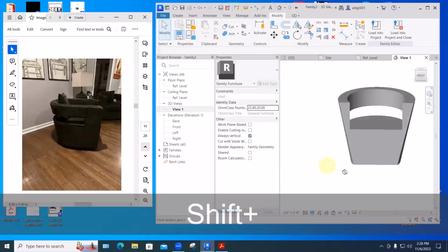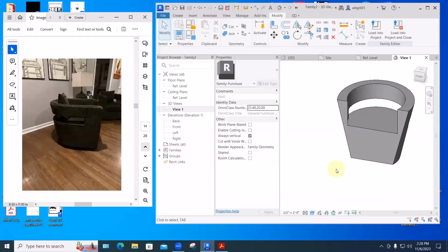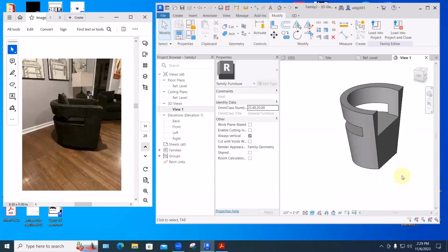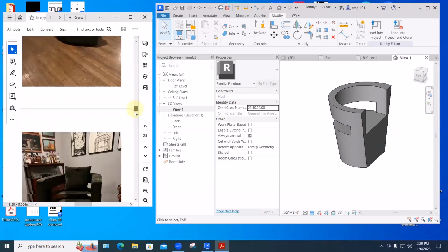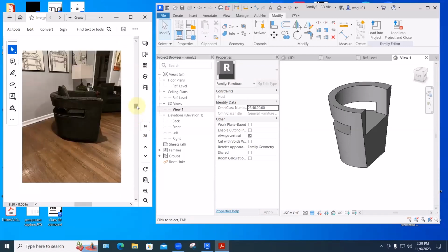Yeah, so to make this as good as possible, this second extrusion would have been tapered as well. It would be not extrusion, but a blend that would also sort of pick up that angle. But we don't want to do all of Connor's work for him here, so we'll just sort of leave this like this. This is where the analytical part of this comes in, of looking at objects, figuring out how we can approximate their volumes with the additive and subtractive tools that we've got. In this case, obviously, there's a lot of simplification, but this isn't too bad for 5 minutes messing around. Well, yeah, it's pretty terrible, actually. We'll let Connor work out the details, but that's the basic idea.